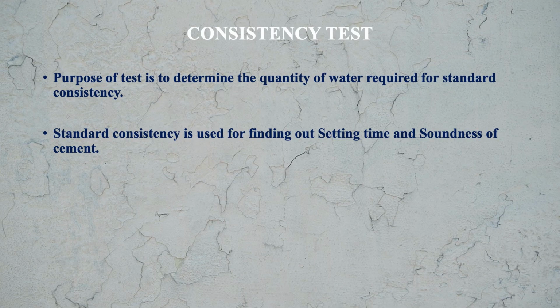So for these tests, this standard consistency test is done so that we can get the quantity of water required for achieving the standard consistency of cement.